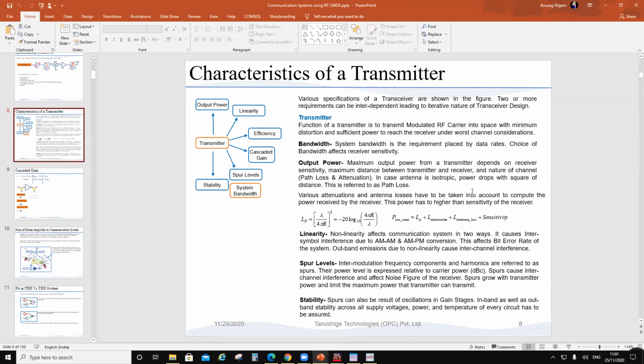Okay, you should understand this. This is a gain, and this is a compression. Gain means it is going to be P out by P in, or P out in dBm minus P in. So that's a gain, while this has to do with the power level, which is going to be dBm, right? So if it's a TOI of 14, what does it mean?